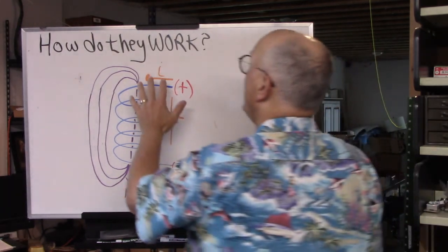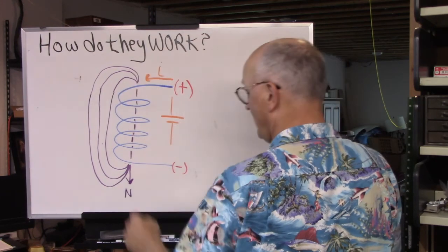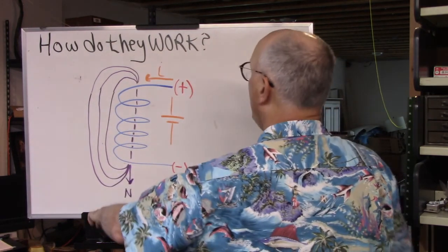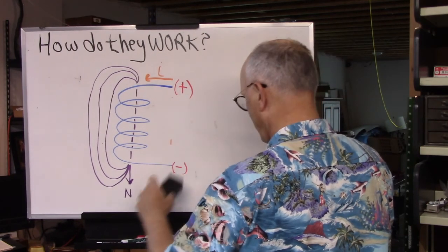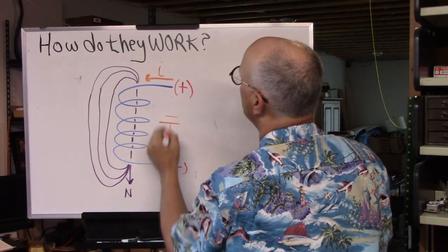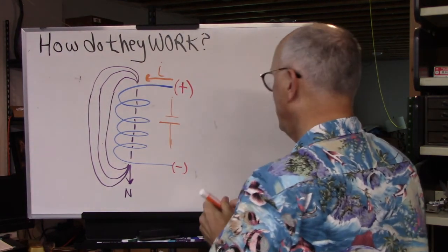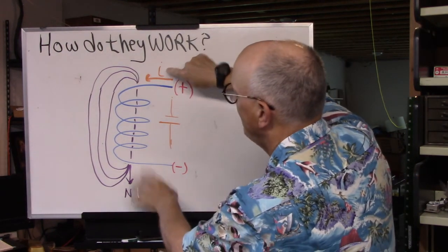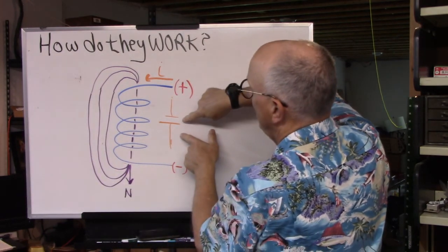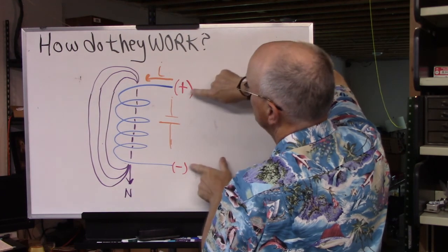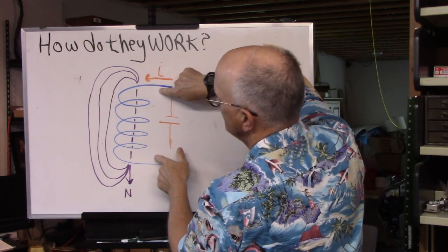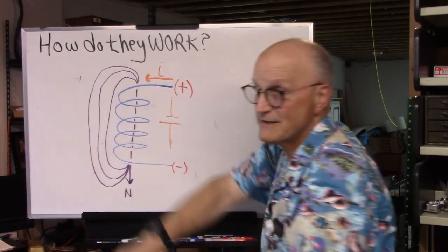And if we're increasing the current, now this north pole is moving the other direction, and our battery flips around, so we have the positive side here and the negative side here. With the current going up and the magnetic field moving away, we have the battery in the opposite direction, trying to maintain this potential difference, to maintain this current, to maintain where it's at.